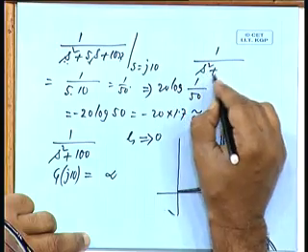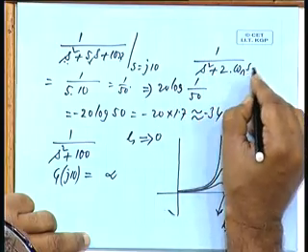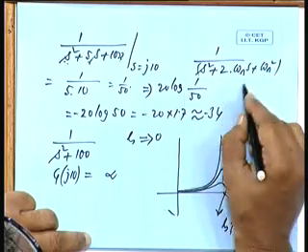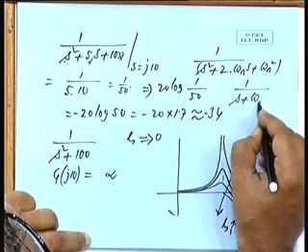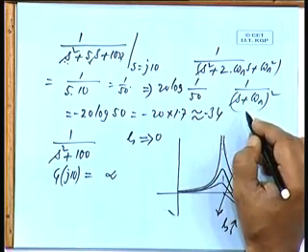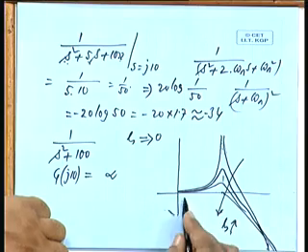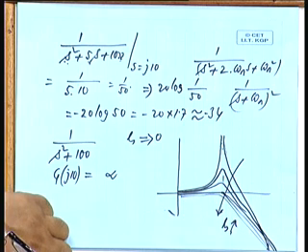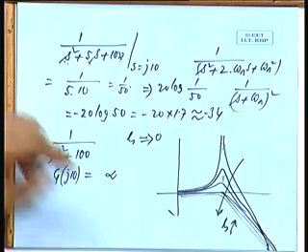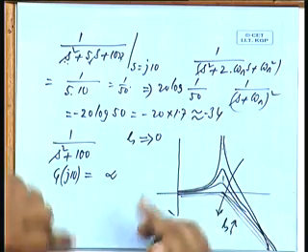When zeta is equal to 1, then it will be 1 by s squared plus twice zeta omega n s plus omega n squared, that means 1 by s plus omega n, whole squared. There are two real, equal roots. So, at omega n, straight away there will be a 40 dB per decade fall. Is that okay? At omega n, two roots are coming.